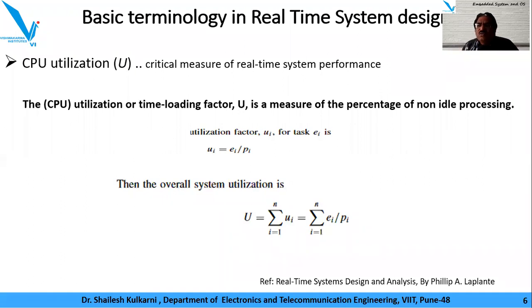In between, some new tasks are expected to be executed, depending on the scheduling policies and on the occurrences of the events for the system. And that is why we say that if the execution time and the period match, it becomes 100% utilization. But in actual practical systems, when you are designing a real-time system, that is never the case.